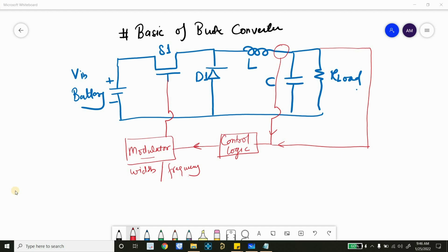On this circuit, the problem statement is the switching part. So we have to tune these three elements, which are the MOSFET, diode and inductor. To tune those, we have to do a few analyses, which will be time domain analysis or transient analysis. After that we'll go for the steady state point analysis, which will be our DC sweep and then AC sweep. So we're going to perform these analyses on an equivalent circuit on PSpice.